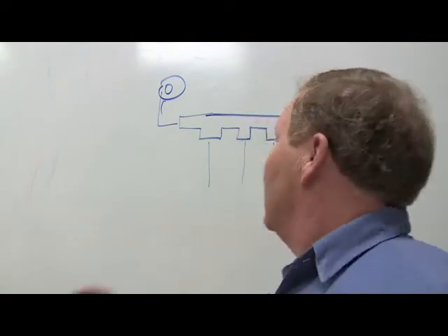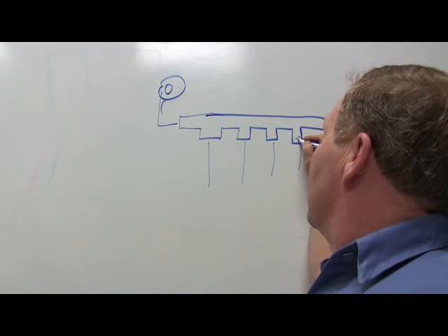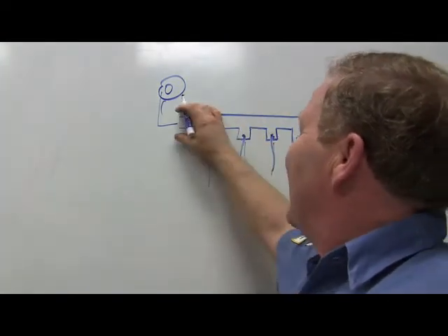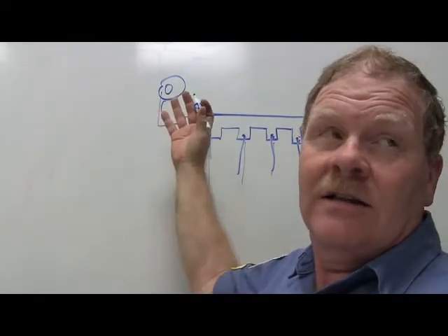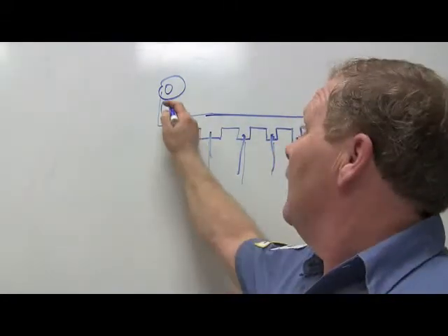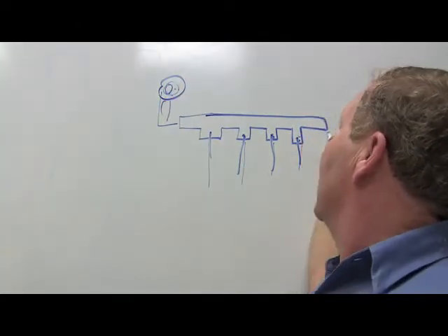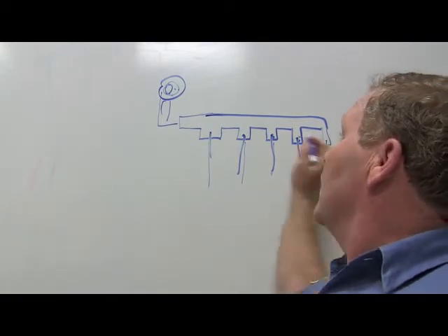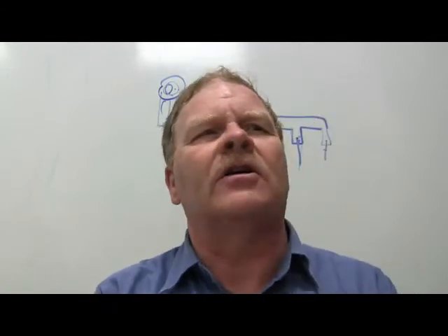So basically, they just have a bus bar, a metal bus bar, and these wires will be crimped just like wire terminals to those. Now a lot of the times this will be in a plastic piece or something like that, so that you're not just looking at a comb-shaped piece of metal. But they'll have the screw and all grounded into the frame, and all of them are hooked together like that. They usually have one over there too, so you'll have a bunch of them. That's a bus bar. It's not there for circuit protection. It's there so you can hook a bunch of other stuff up.